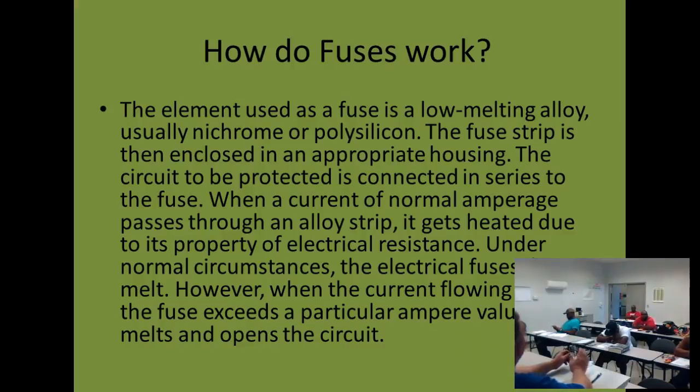You know, as y'all do more and more work, you're going to get an idea what things, you know, like a compressor may read 2 ohms on the start, maybe 3 ohms on the start, and 1.5 on the run winding, and a 5 kW heater, and you go, hey, that's about 9.5. But y'all don't know that. All y'all know is it has resistance, and so for now, we're just saying it should have measurable resistance. As you get more experience, you may go, hey, I've never seen one that high or that low. Okay?